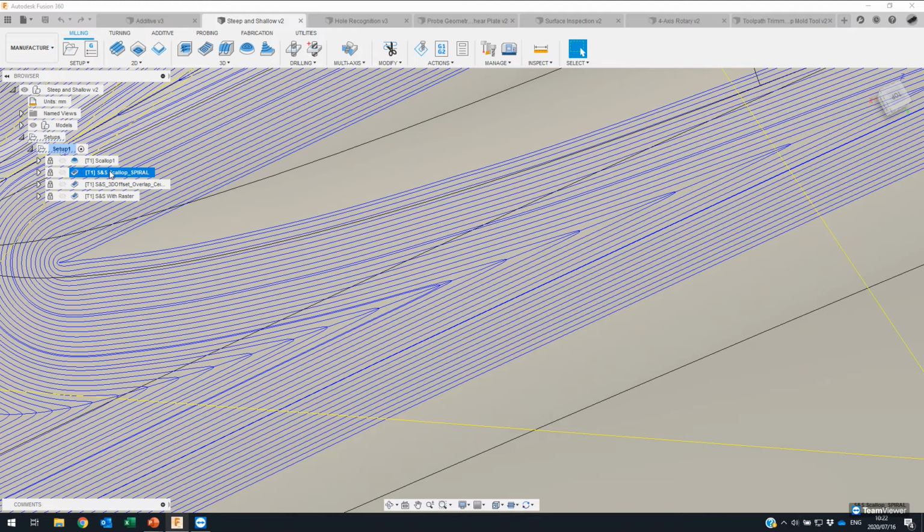And we can see that that is a much smoother toolpath. It will result in a better surface finish. And one thing you'll notice as well is at those apexes where the tool turns, it's a much smoother turn. And there is a toolpath that actually flows through each of those apex points.